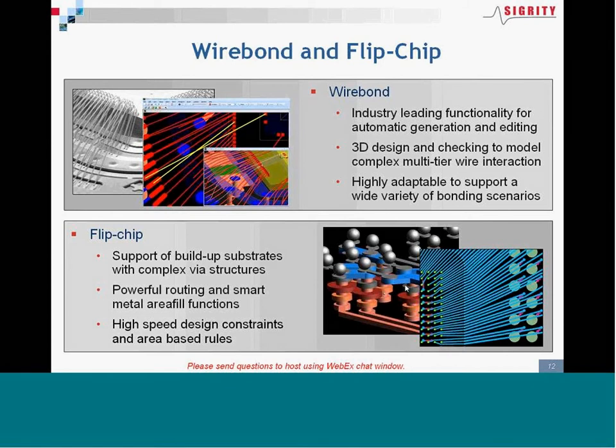For flip chip, we support a wide range of technologies, including build-up substrates using a stack-up similar to a 3-2-3 type stack-up. We also have some nice capability to manage and route high-speed signals or differential pairs that are fairly common on these types of designs.